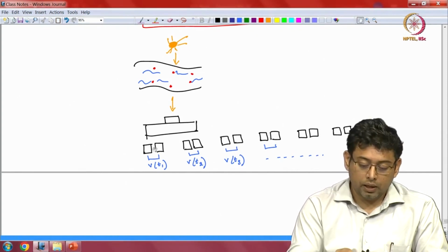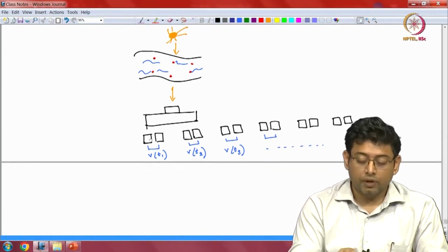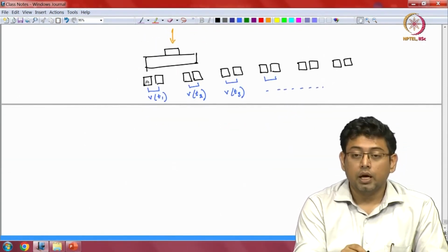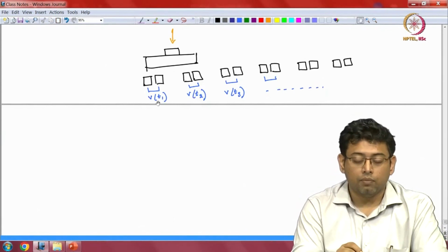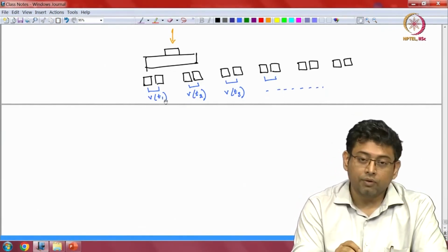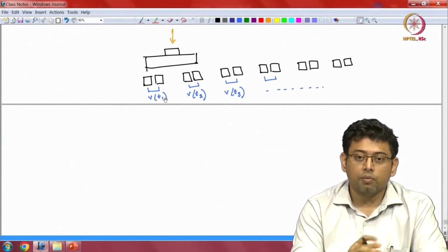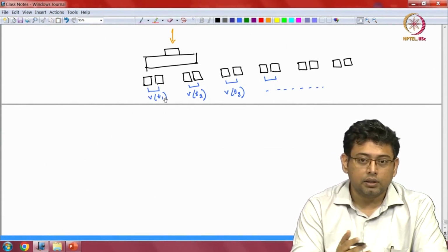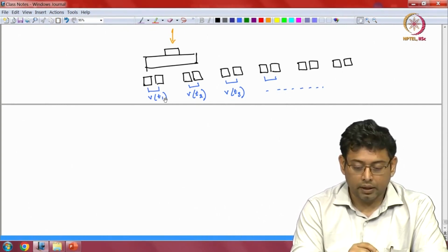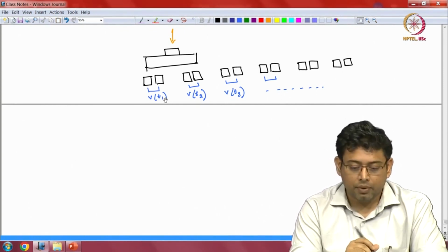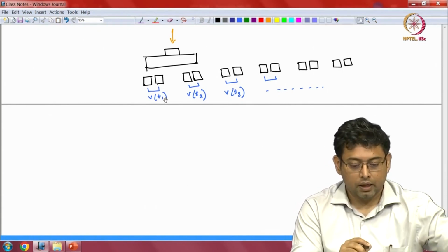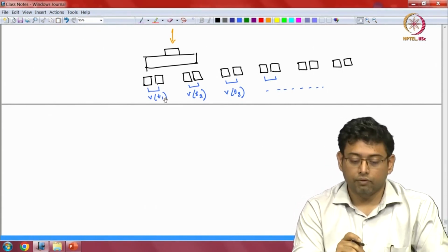So for most conventional PIV operations, you do need image pairs like this. However, when the flow is laminar and steady, you might be able to get away with just a normal DSLR camera and just a traditional recording in that case. This usually happens for microscale flows quite a bit, where the flow speeds are not necessarily very high.